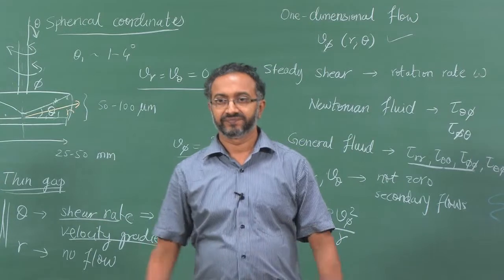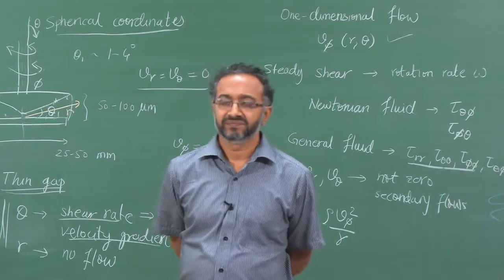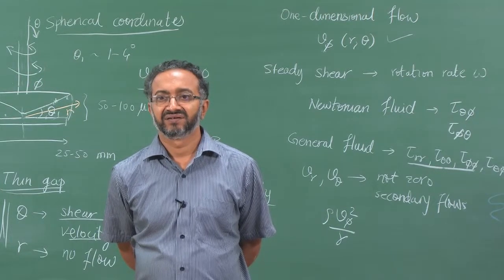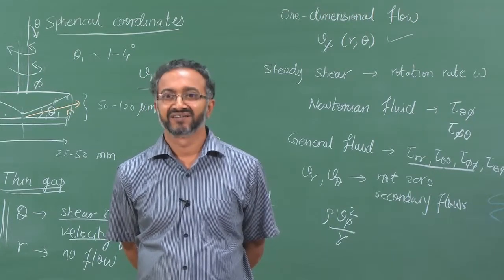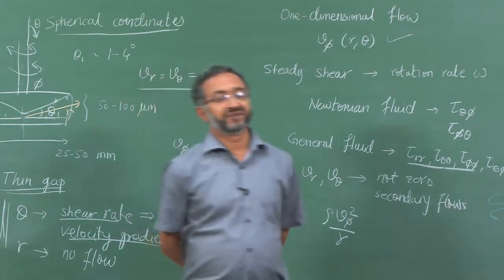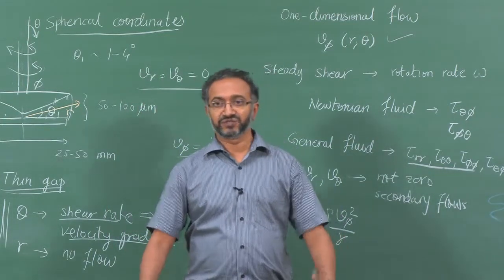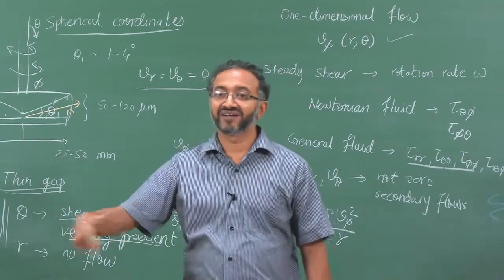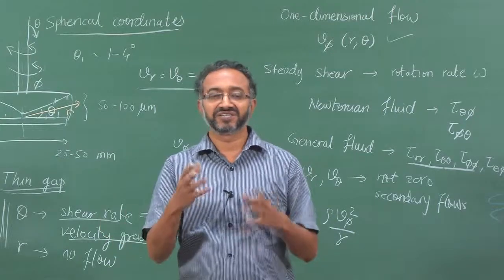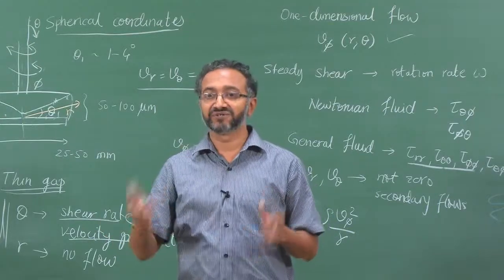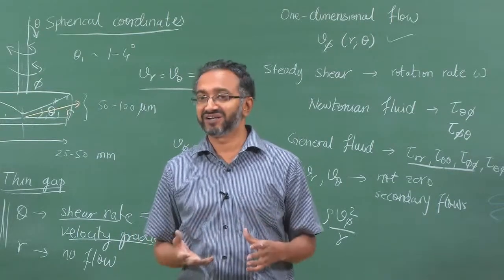Sir, for some time we are doing the experiment at constant shear. Right. So, the initial value of eta will be higher, and we will not take the data from there. Right. But if, let us say, you are examining nonlinear viscoelasticity, you would want to take the data of eta increasing and decreasing. We said stress growth. Yes. So under those cases you want the changing value of viscosity as a function of time to analyze material behavior.